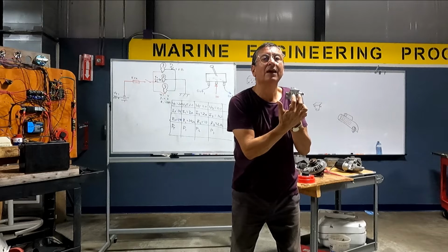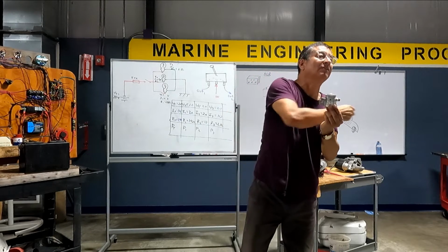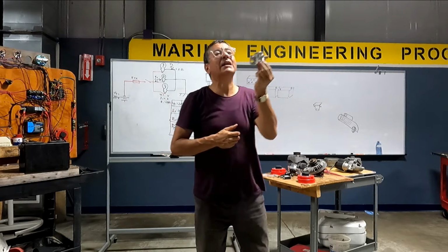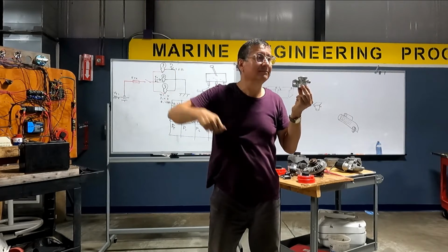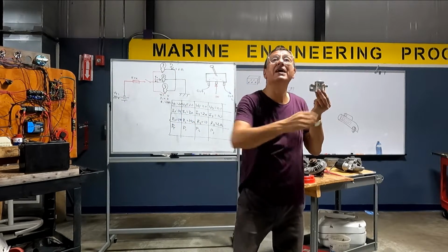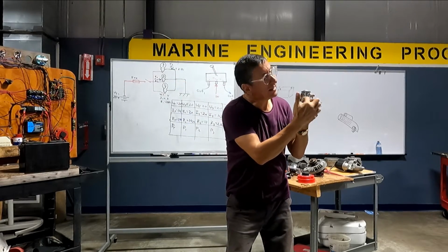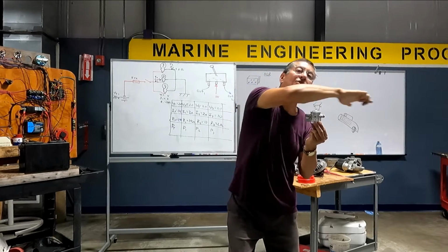When you bring the signal, a magnet internally closes the gap and the current passes to the second one. This is the relay. The relay is a remotely activated switch. It's a switch that I activate from another place. I bring a signal here, the coil creates a magnet, the magnet closes the gap, and the current passes from this point to this point.